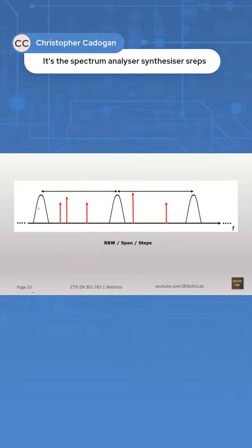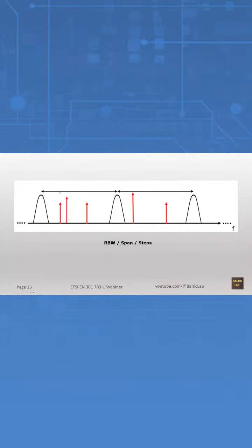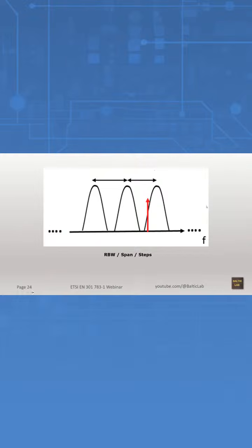The distance from each one of those humps, those are the sampling points, is going to be 100 kilohertz. Any signals in between are going to fall outside of it and are essentially invisible. Now you're going to ask, but it wasn't invisible, it just showed at the wrong frequency. Yes, because the 3 dB bandwidth of this Gaussian-shaped filter is the frequency given. So the 3 dB bandwidth is 100 kilohertz.